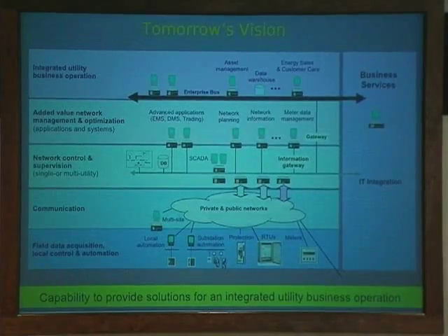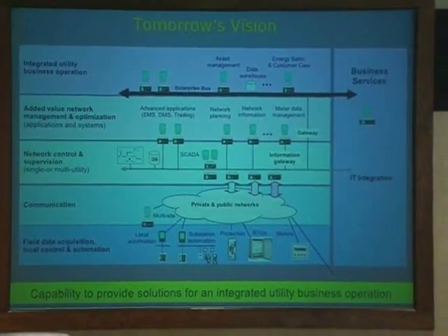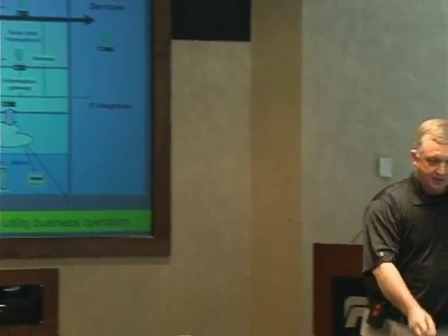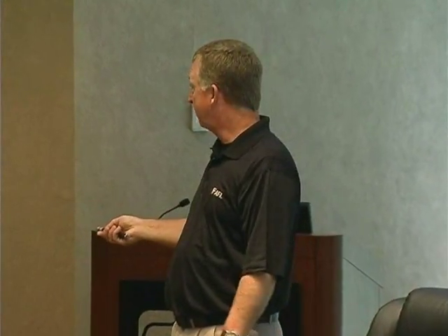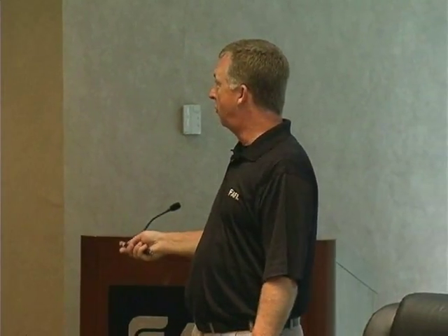Well, really, it's not just a system to monitor that by itself. It's part of the full integration of business services for the utility. If we follow this little diagram from bottom to top, these are the devices that are out in the field. It could be the meters. It's the RTUs that are in the substations or out on the distribution or transmission line. It's the devices in the switch house. Those devices have got to talk back to some central location through a network.